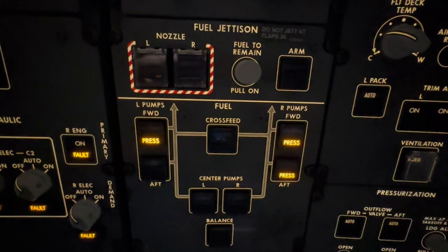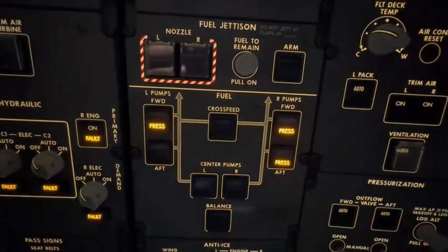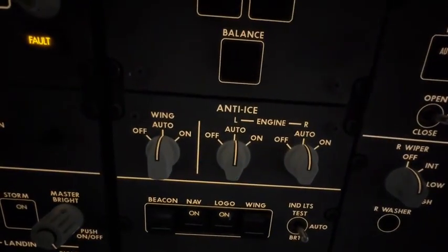The reason you see the aft left pump not illuminated is that there's no pressure signal on it because the APU is running. It automatically turns that pump on no matter what. Another little fun fact for you: you don't need the left or right wing tank pumps running for the engines to run. If they are not running, the engines will automatically pull the fuel out of the wings via suction. Gravity is a beautiful thing.